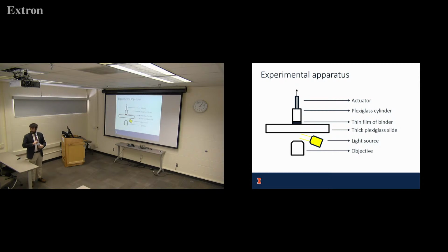Just one more for all. Yes. So how do you make sure that whatever you see as damage at the microscale level also applies when you have a mix? Because the crack might initiate at the contact between the binder and the aggregate, which might change the results that you see. The ranking of binders might be different when you include them in a mix.